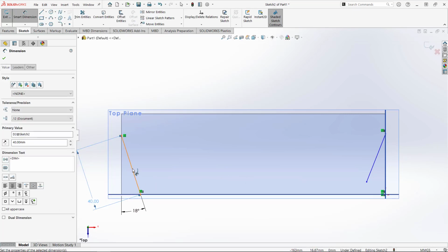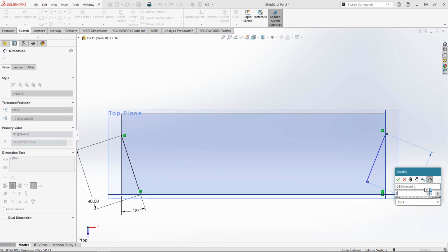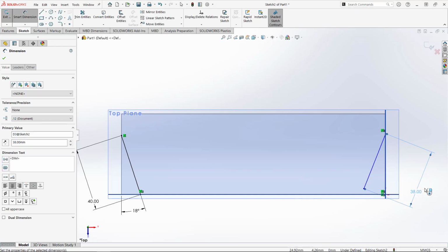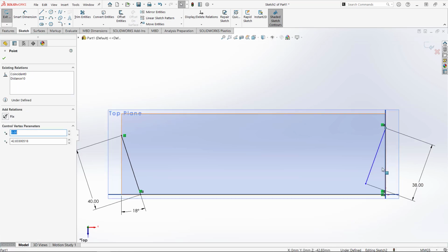So the position and scale of this line on this end, the left hand side, is fully defined. The one on this side, I'm going to partially define for the time being, but my intention there is to come back further on through the design process and fully define that particular line. So you can see it's free to move up and down to a certain degree, and it's free to change its angle as well.